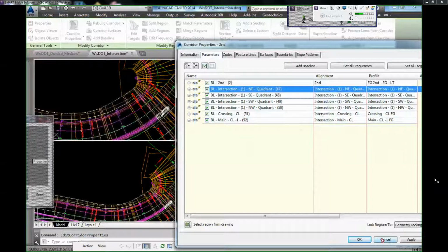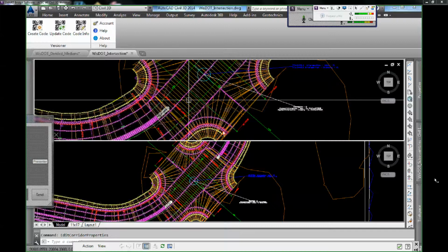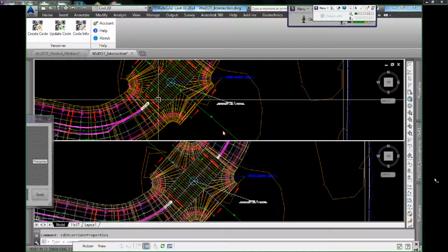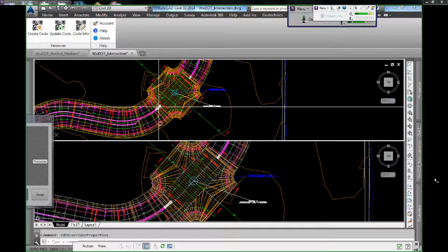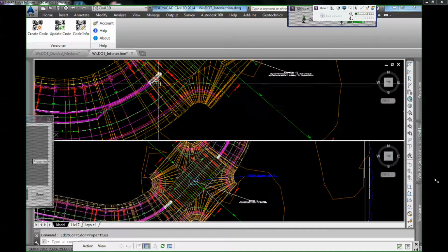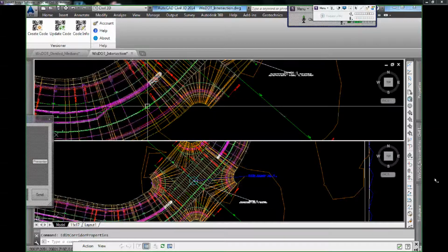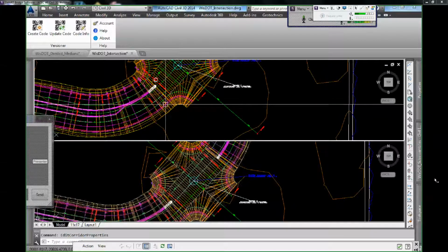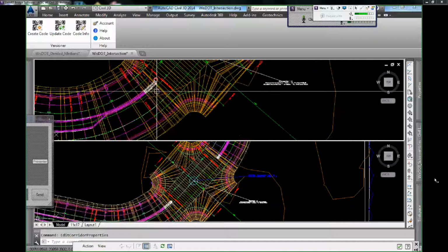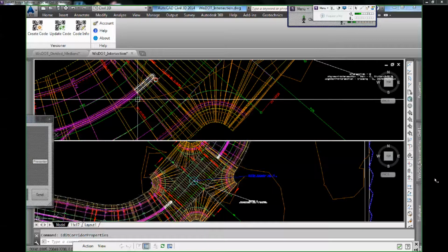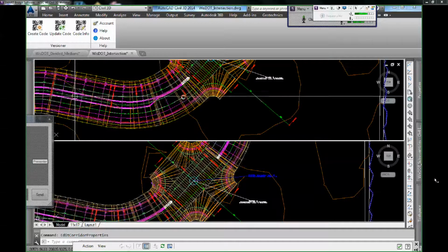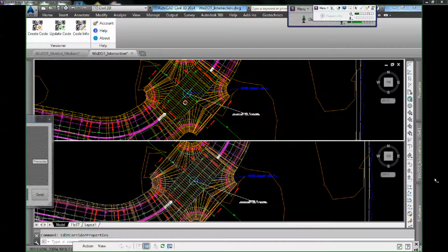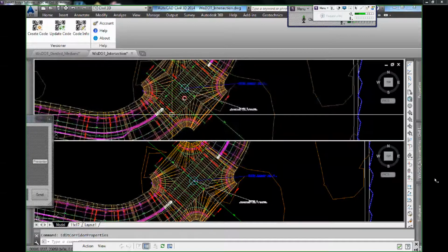Nothing real special here. Now, what I had to do though, a little retrofitting here, because when you use the intersection tool, you have to have an alignment going down the center line. Well, my alignments are going along the center line of this road, and you can see it here. And so the fun begins trying to get these two to match at the critical match line here, which in this case is right here. Okay, because there is no reason to try to make the corridor build all the way through this intersection because it just can't do it, okay? And it cannot do the bullnose.